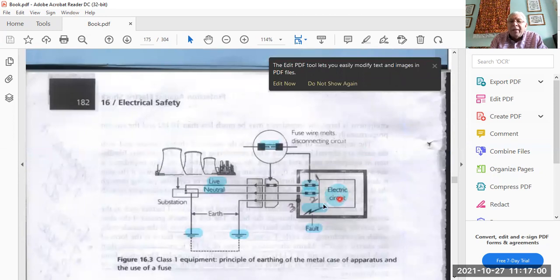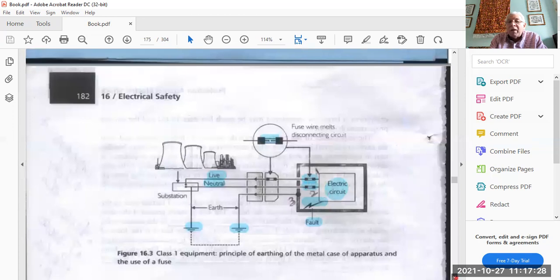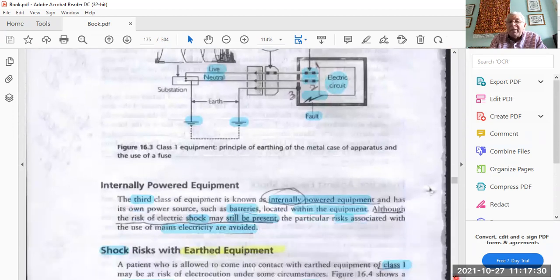I apply what we call fuses. As you see, 2 fuses on the neutral and the live, and we have an additional fuse on the socket. So whenever this short circuit occurs, heat, of course, as you know, electricity creates heat. This heat is capable of cutting off this current by melting the fuse. So this is the earthed equipment, how they are utilized to guard against electric shock.